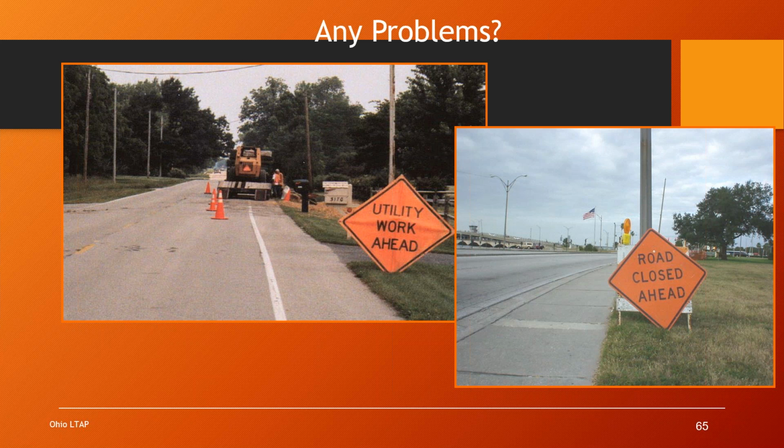Well, the point I'm making here is I'll just tell you it's a flagging operation is what they should have been setting up for. So in a flagging operation, you follow along with typical application number 10, and that shows a minimum of 3 advanced warning signs. And we really want you to use 4. So we want you to include the be prepared to stop sign as well, and the flagger would be well in advance. There would be no sign right here.